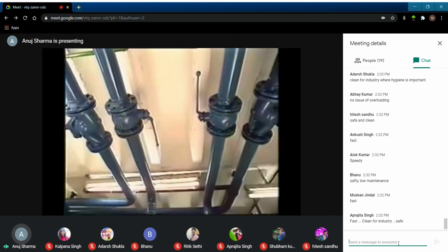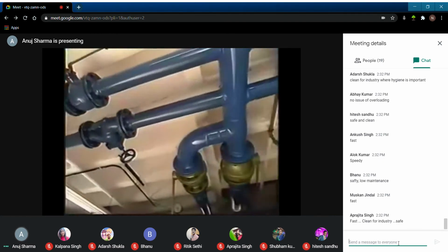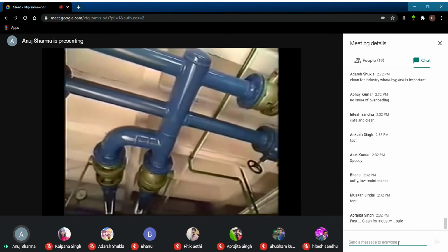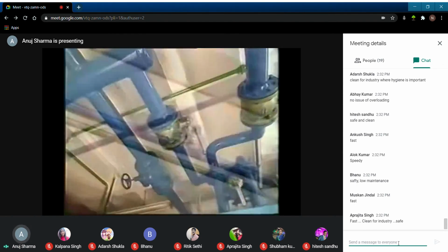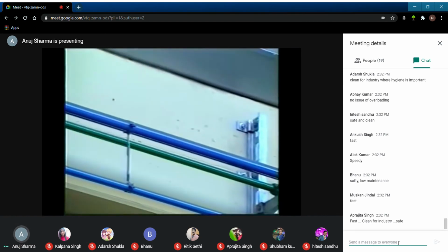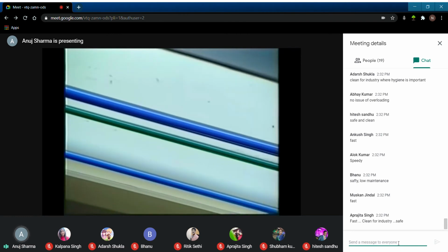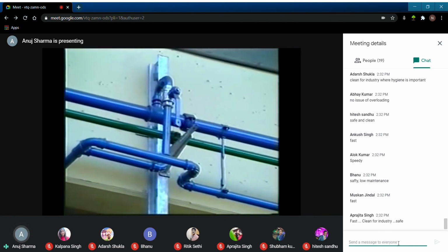The size and layout of the pipes is critical for economical operation of the system. The design should also allow for future increases in demand because modifications can become very expensive. Connections to the main piping should be done from above to prevent water from flowing into the machinery. The system should also include fixtures that allow water to be drained off.